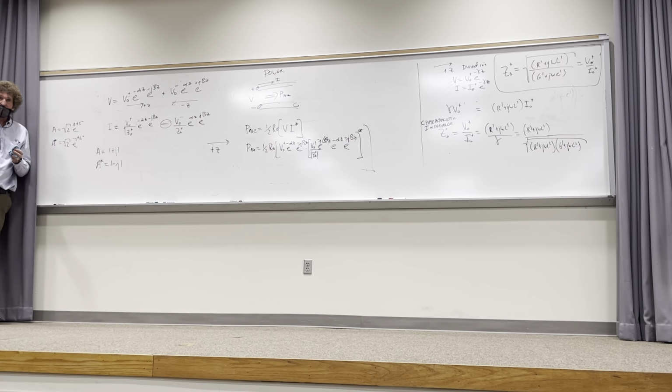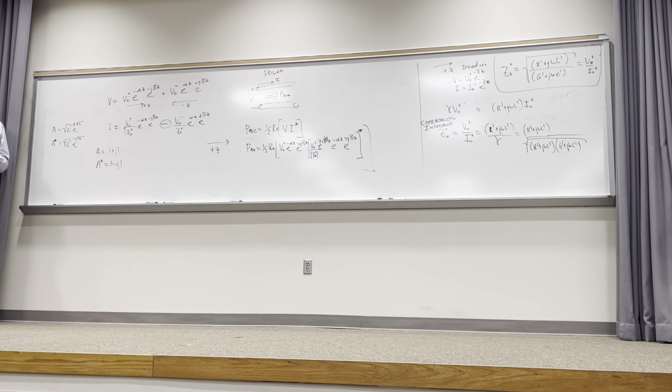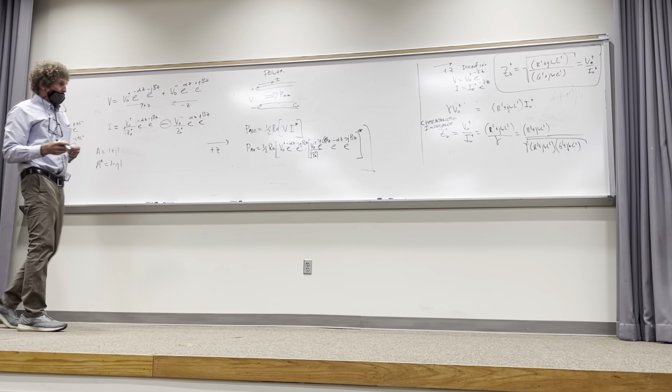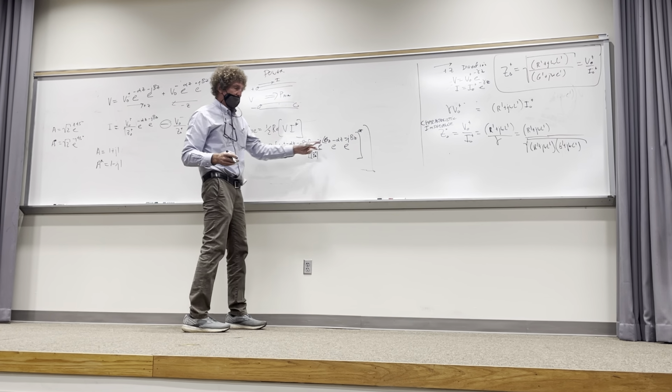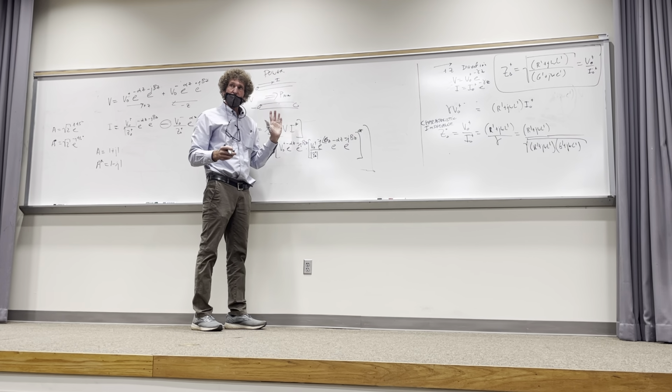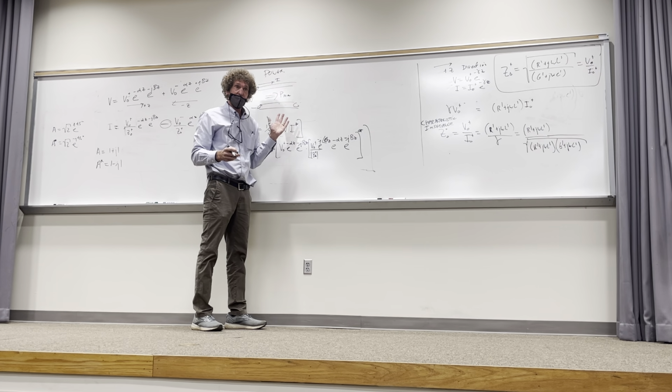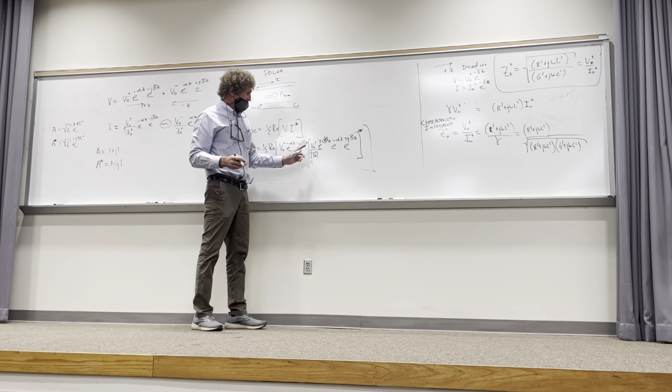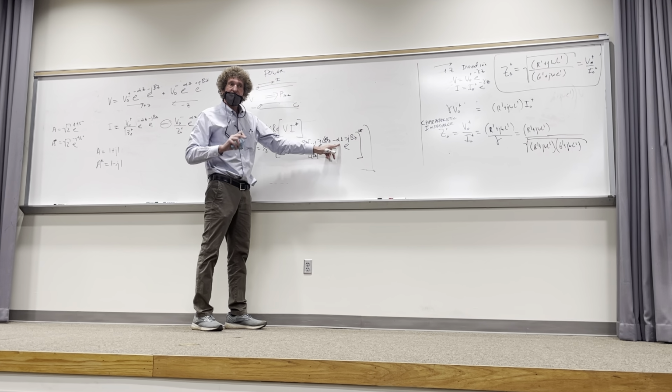Y'all follow me in that class? That's conjugation. This is a term that you're going to hear over and over again, so you get familiar with it. When I take the conjugate of this, all the real terms, that means no j's in them, you don't do anything for it. That means the V0 plus, the magnitude of Z0, and e to the minus alpha z you leave alone.